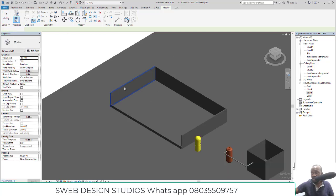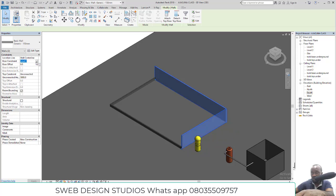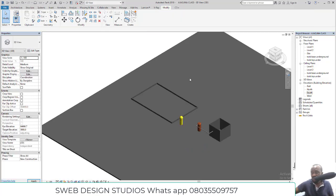Okay, now it didn't really work as I want, so the best thing is just come here. See, it has a height of 3000, though, but it's not connected to the level that I want. So I'll come here, I'll select base constraint, do the same thing here, top. Then I'll select, let me just select this, hold my control key so that I'll just do everything once. The base should be underground tank, then the top should be connected to the tank top. So that does it.